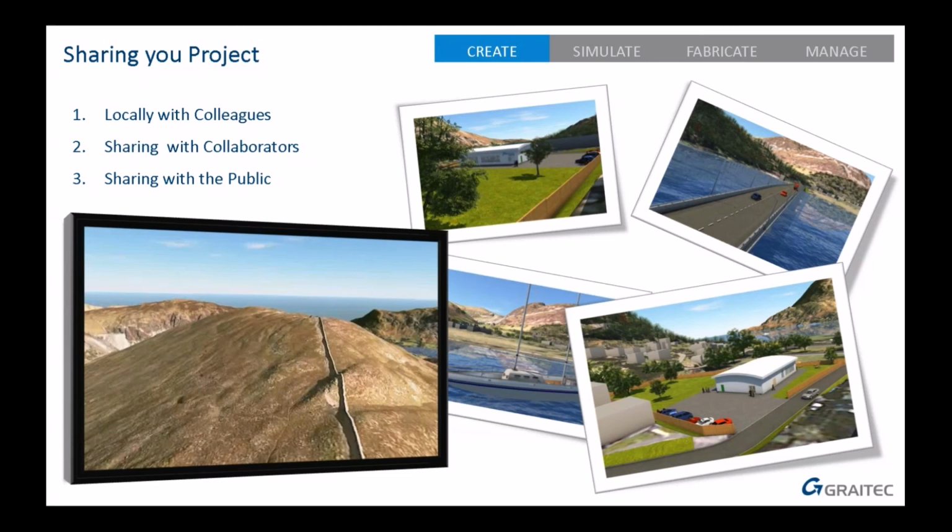Okay, right. Drain pipes. Pipes can go straight into Civil 3D from InfraWorks, and then yes, you can put them in. For structures, if you put a bridge into Civil 3D, it comes in as AutoCAD solids. So yes, you can bring them in, but they are AutoCAD solids.